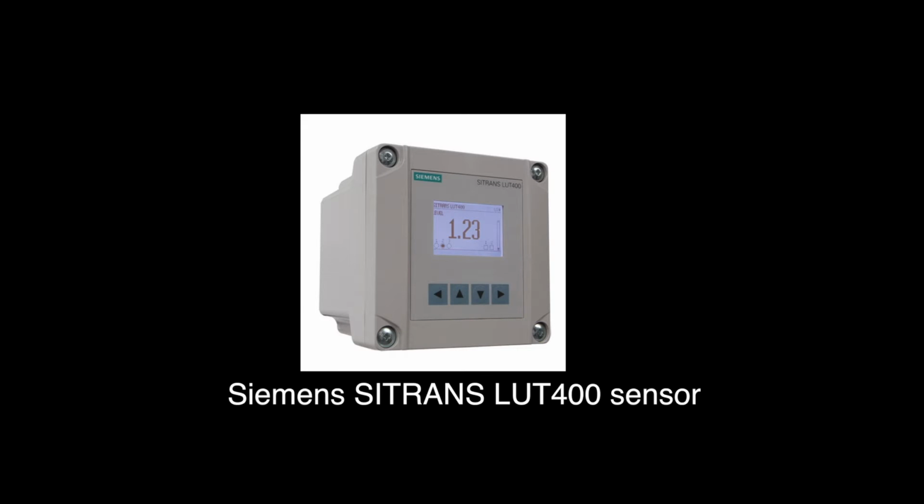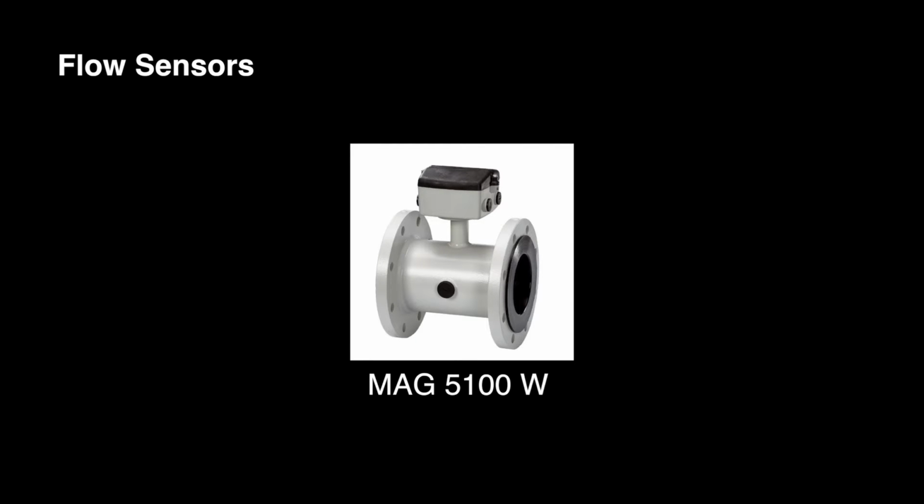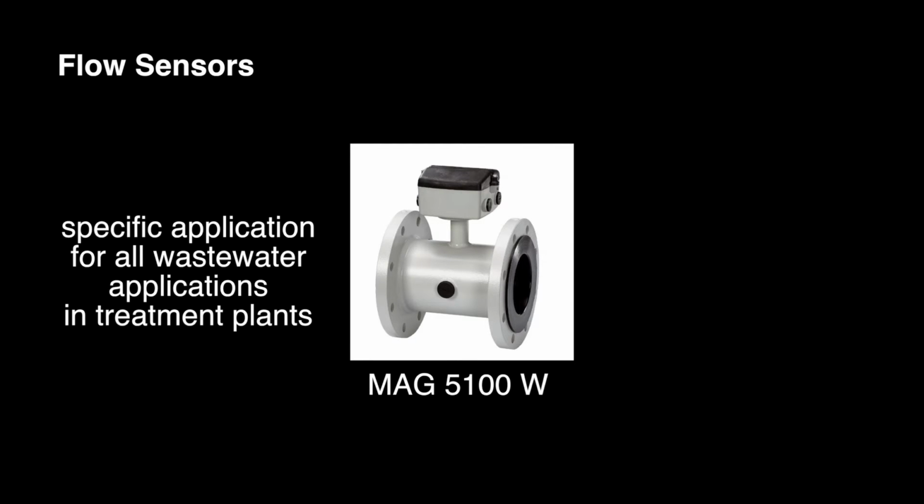Based on the guidance of the chart, the Siemens SITRANS LUT400 sensor is chosen for the process. It also comes with advanced pump, alarm, flow control features and energy-saving algorithms. For flow sensors, the MAG 5100 W is chosen based on its specific application for all wastewater applications in treatment plants. Now for the next part, I'll be talking about how the system of sensors and PLC would come together to optimize the process.